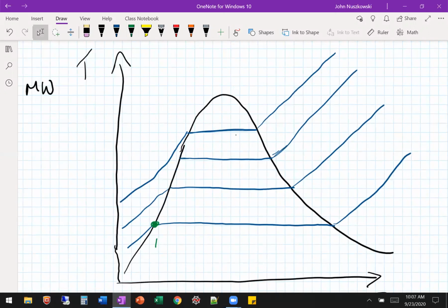Then we isentropically compress to state 2, okay. State 2 is in an open feed water heater, so that's mixing with everything else to get the outlet of 3, okay. But 3 is the inlet to the next pump, right, pump 2, okay. So that means we have to start for 3, quality of 0, okay.